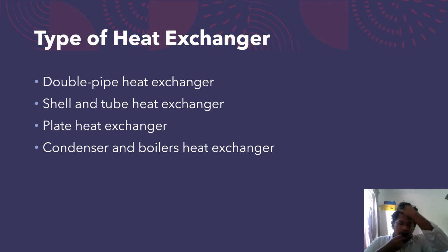The main constituents of this type of heat exchanger seem to be the tube box, the shell, the front and rear end headers, and the baffles or the fins. So the third one is the plate heat exchangers. A plate heat exchanger contains a number of thin shaped heat transfer plates, bundled together. The gasket arrangement of each pair of plates provides two separate channel systems. Each pair of plates forms a channel where the fluid can flow through.